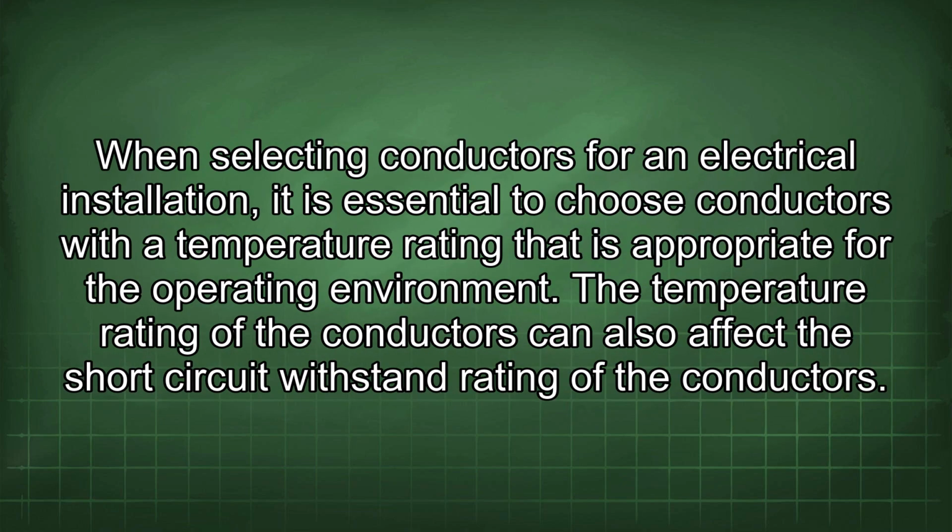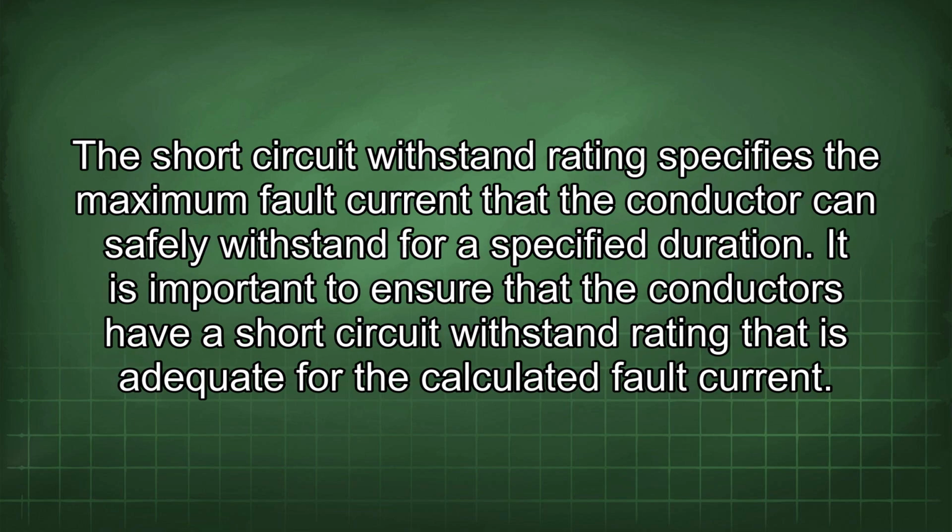When selecting conductors for an electrical installation, it is essential to choose conductors with a temperature rating that is appropriate for the operating environment. The temperature rating of the conductors can also affect the short circuit withstand rating of the conductors. The short circuit withstand rating specifies the maximum fault current that the conductor can safely withstand for a specified duration.